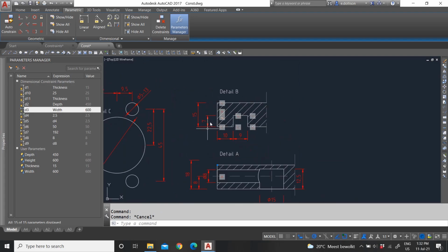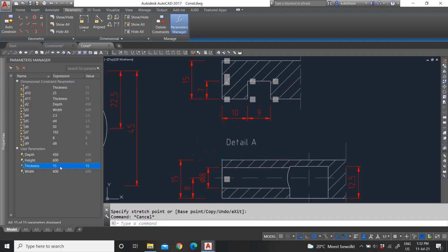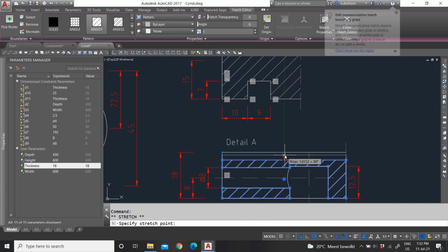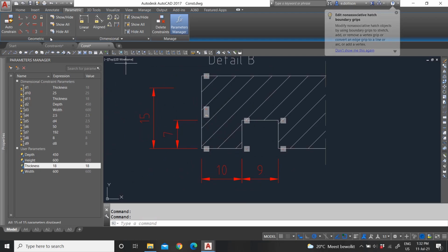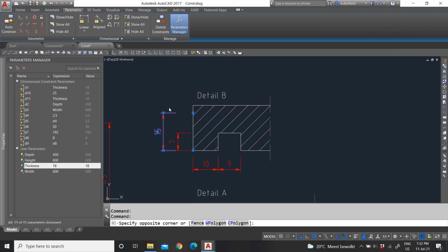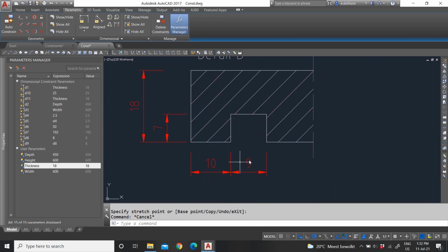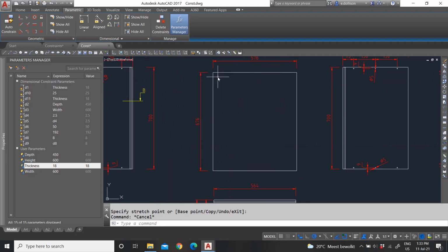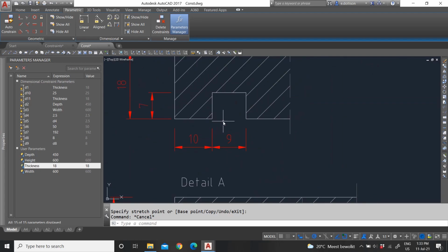And the reason why this has become 15 instead of 18 is because, of course, my thickness is not set to 18, but it's set to 15. Let us go back to 18. And there we have it. Okay, so let us get into the parameters, how we set our parameters. And here we can see our groove, first of all, is 9 millimeters wide. And the reason why it is 9 millimeters is because my back panel is actually 8 millimeters. So we have a spacing of just 1 millimeter.